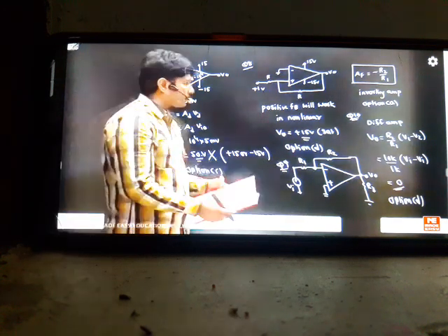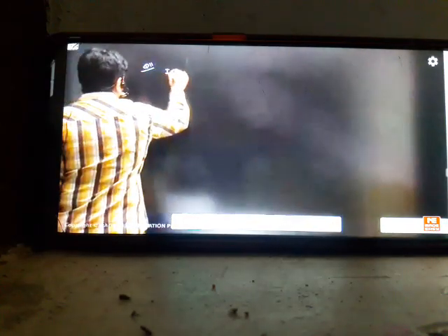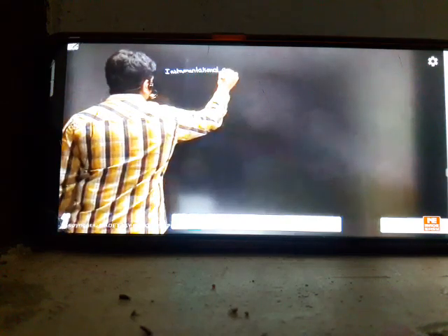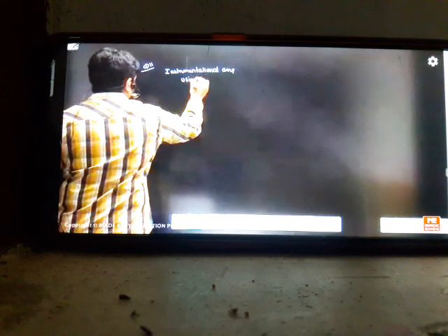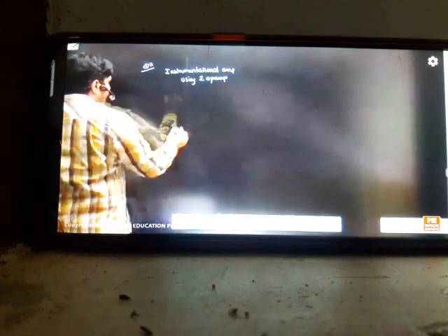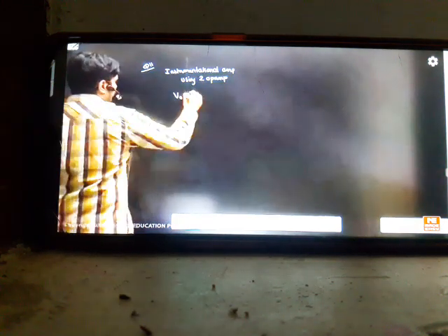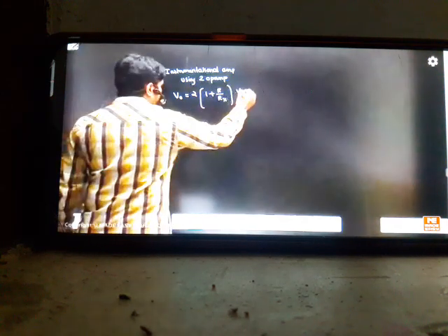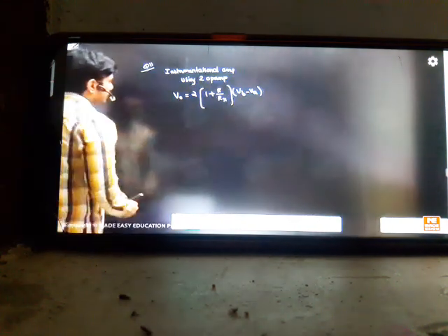Then we should not do calculations. I said straightforwardly you have to complete the answer. If it is question number 11, if you can recollect that it's an instrumentation amplifier using 2 op amp circuit, the formula is very easy. It's a 2 non-inverting gain formula. He's asking only V0. So the V0 formula is 2 times (1 plus R by Rx), that is a 2 non-inverting and 2 times multiplication, times VB minus VA. If it goes like this, hardly 10 seconds and this problem will be completed.